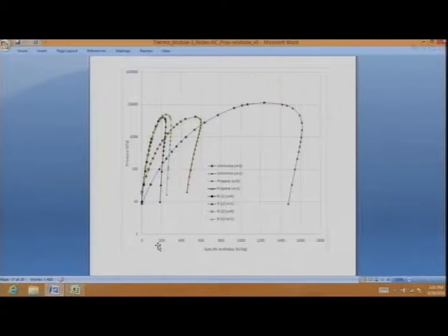Water tables that you see, there the specific enthalpy of saturated liquid water at triple point is set to 0. So I cannot just make that plot and plot H of that on this. They will look fine, okay, but actually they are quite different there. The whole thing will have to be shifted quite a ways out.